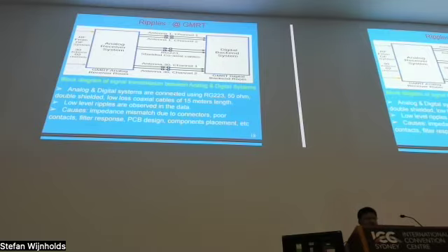So this is the actual transmission line in GMRT. There is an analog receiver system in one room and a digital backend system in the next room. These two systems are connected using RG223 50 ohm double shielded low loss coaxial cables of 15 meter length. In between there is a connector also. These connectors are required to separate the grounding of both the systems.